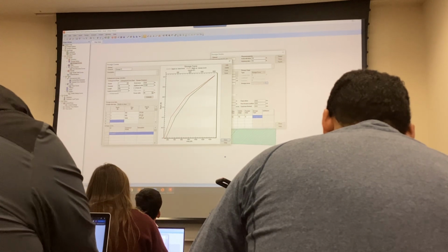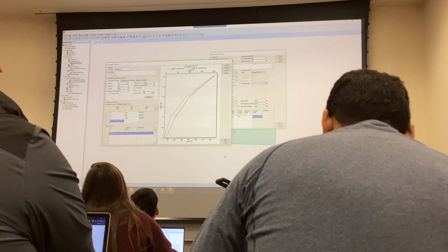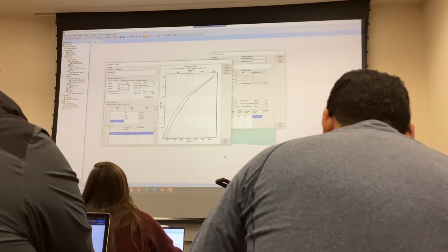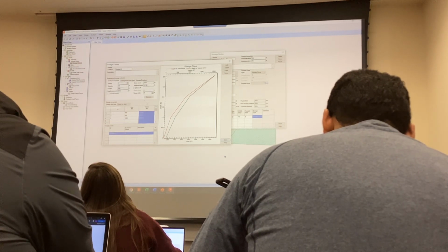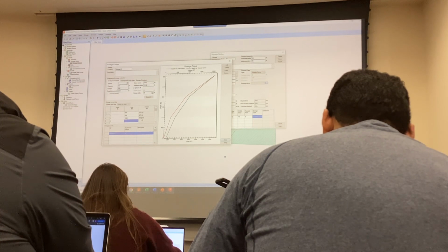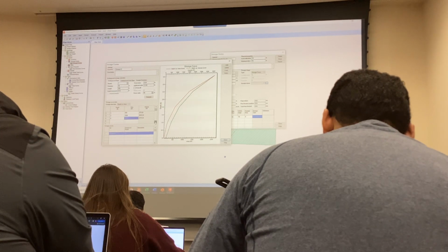And how deep was our detention basin, by the way? 6, right? Because your invert is 10 and your maximum is 16. So I can only go up to 6 for my curve. So at depth 4, I'm going to specify 2600. Now you don't need to copy my numbers because I'm just making things up over here. You pull this information from your AutoCAD.